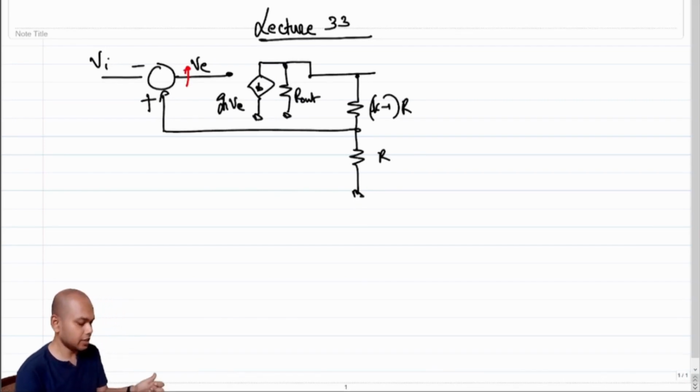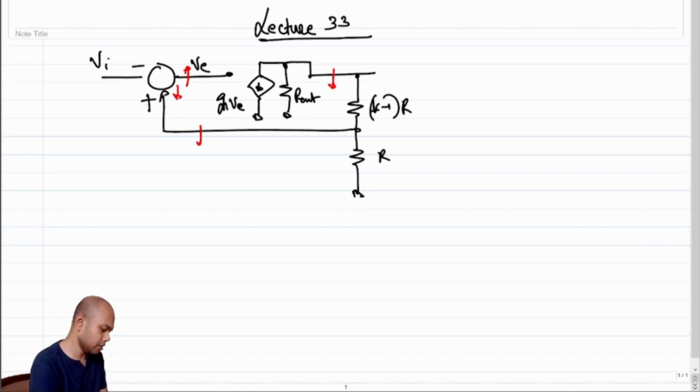This voltage, let's say it increases because of some injection, this voltage increases. So this decreases, so this decreases. As you can see, if I inject any disturbance in the loop externally, then the loop has an action of reducing the disturbance. So this is negative feedback. So the signs are all right.